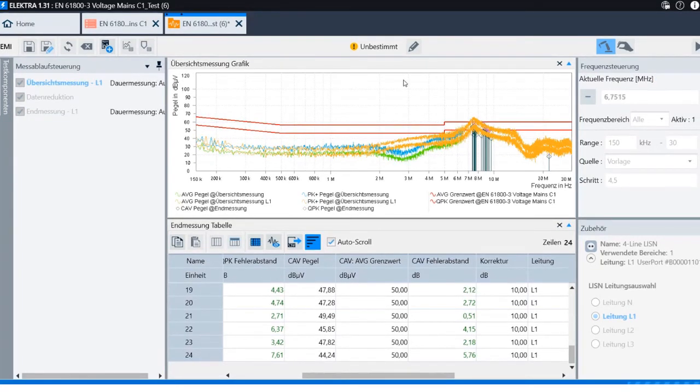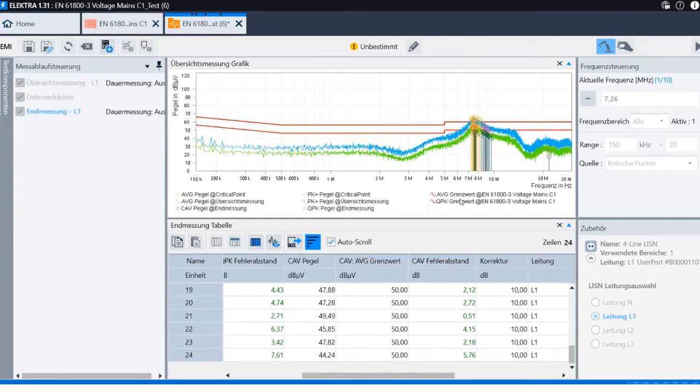Here we can see the last measurement in this range of tests. So now we have connected the shielding on the motor side again, and now it's disconnected on the drive side. And the picture is more or less the same, but a little bit different. So it's just to show you that it depends a bit on which side the shielding is connected. It's best to just connect it on both sides to have a reasonable disturbance limiting effect of the shielding.